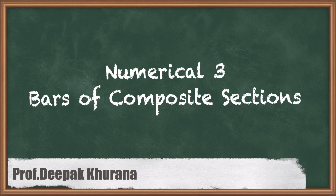Take the modulus of elasticity of the material as 205 GPa. This is again the question of bars of composite section, in which we are given a bar which is 0.8 mm above the ground. So there is a gap and a load of 40 kN is applied. When we apply the 40 kN load, first there will be a gap filling in this system, and then the stresses will be developed in the material.